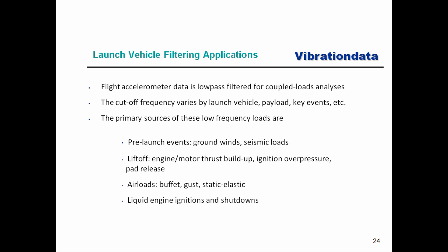There's also liftoff events: engine and motor thrust buildup, ignition overpressure, pad release. During powered flight and ascent, there's aero loads, buffets, gusts, static elastic, maneuver loads, and so on. And there's also things like liquid engine ignitions and shutdowns. Sometimes you'll hear main engine cutoff effect. There could be some oscillation effects going on.